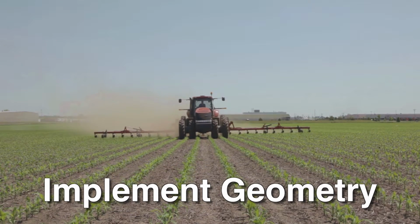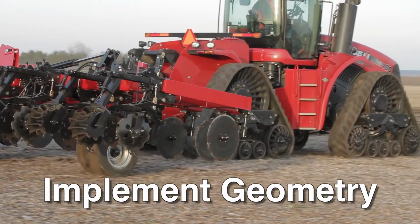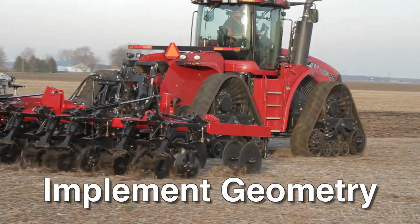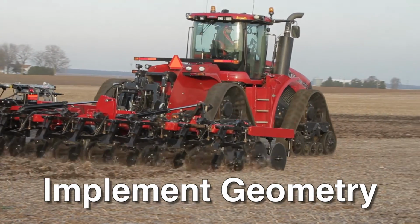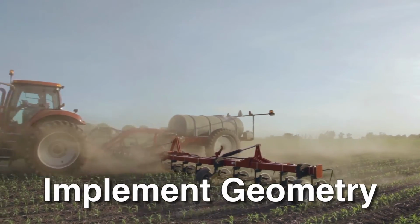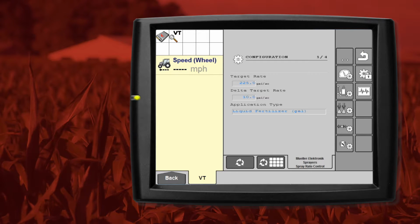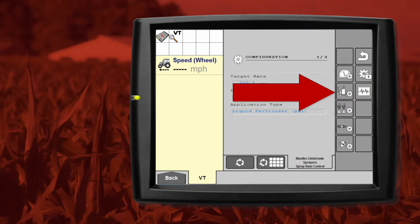Let's now tell the system about your implement geometry. The geometry is the number of parameters which describe the dimensions of your implement. Inputting the geometry enables the system to know the exact length and width of the machine and the position of the individual sections. Press the back arrow, select the geometry settings icon.